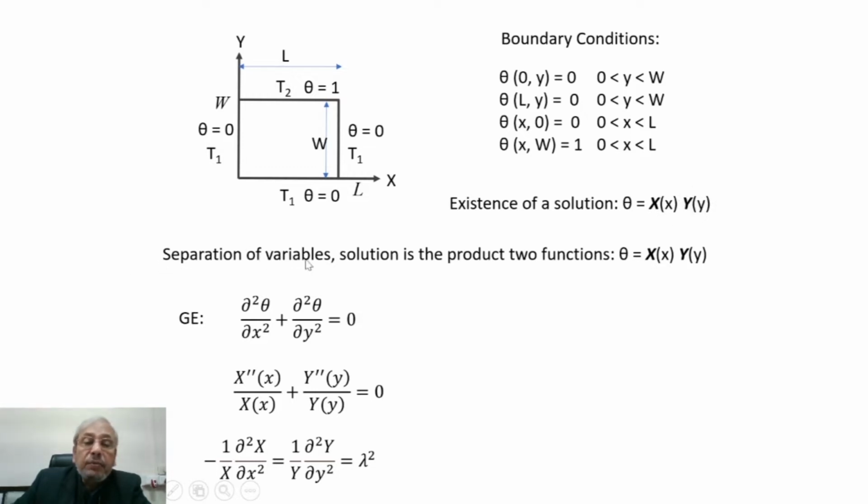So separation of variables we will apply. Basically, in this technique, solution is the product of two functions, uppercase X, which is a function of x, and uppercase Y, which is a function of y, and the product of these two functions will give theta. Product of uppercase X and Y will define the final distribution of theta.